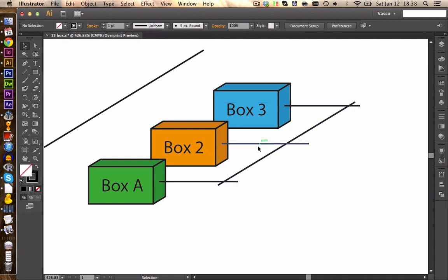And if I want to have those aligned perfectly to these connections, now I will select one of those lines and I go to my scissors tool. You find this under the eraser. Just click and hold on the symbol. And I'm just going to cut the lines so we don't have these overstanding pieces here. Let's also do this for the other lines over here. You can also press C to get to your scissors. Now I go around and delete all the pieces we don't need.